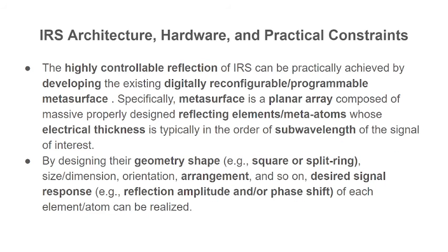IRS architecture, hardware, and practical constraint. The highly controllable reflection of IRS can be practically achieved by developing the existing digitally reconfigurable programmable metasurface. Especially, metasurface is a planar array composed of massive properly designed reflecting elements, meta-atoms, whose electrical thickness is typically on the order of subwavelength of the signal of interest. By designing their geometry shape, the desired signal response can be realized.